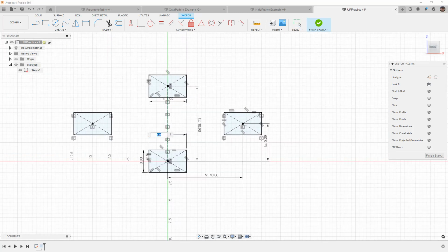So for example, the box width, I'm going to start typing B for box, and we're going to figure out if this is length or width. You'll notice here we don't actually have a numerical value, so this is why using the numbers or using the logic of the naming convention is going to be important. And if we relink this one, we're going to call this one box width. Nothing changed so far, but if we take a look at this, you'll notice that it's linked to D4.